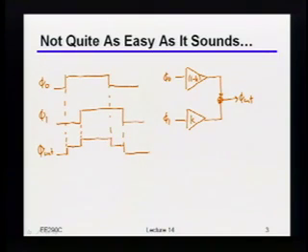Signal is no longer a clock. Okay, you're right, it's no longer a clock, but let's say I squint my eyes and I say, okay, if I blur this out enough, it kind of looks like a clock. What's really bad about this particular clock? By the way, it all has to do with the fact that it's not really a clock and you can't really exactly define where the phase is.